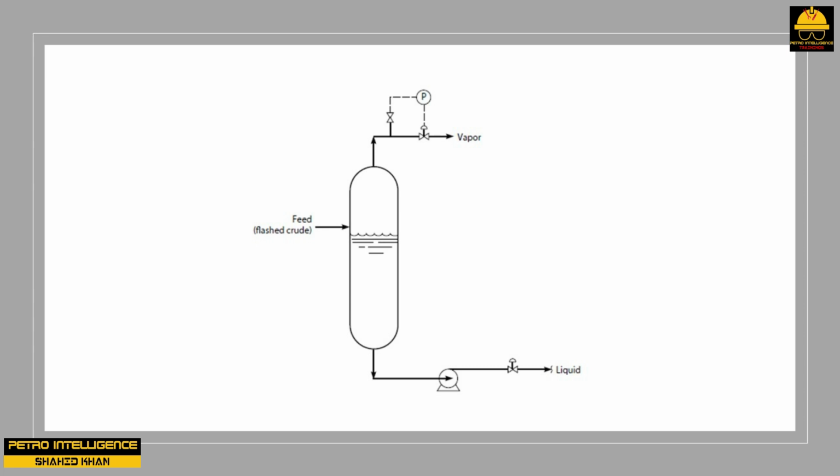The operators had then started the motor driving the pump. Next, they very slowly opened the discharge valve. Regardless of their efforts, the pump cavitated so badly that it could not be put in service. Some pumps are like that. The design engineer just never allowed any extra liquid elevation for the starting NPSH. But what could he do? You see, guys, here is the problem. The pump needs to be started on an urgent basis.